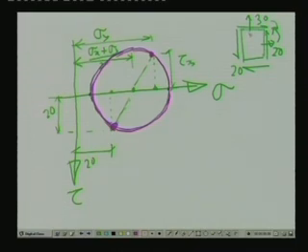Now, we are interested to evaluate the stress at a plane which is making an angle of 30 degree with x plane. Eventually, that will make 60 degree in the Mohr circle. So, with reference to this line, say line OA, if we represent that plane by this point, let us say C, this particular angle is 60 degree.